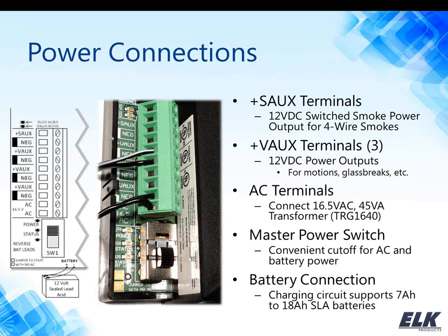And that's a great way to reset those 4-wire smoke detectors that we were previously talking about on the other slide. Again, there is a power switch, so if you do need to make a connection or change something, it's extremely convenient because you can just take the power off the panel right there.